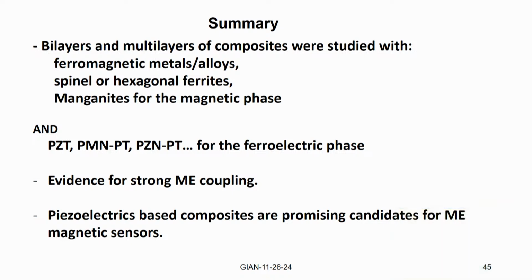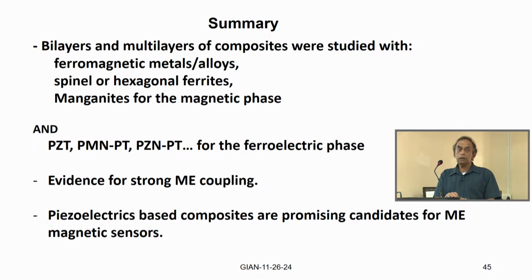To summarize, I discussed the magnetoelectric bilayers and trilayers based on PCT, PMN-PT and pure piezoelectrics, with a variety of ferromagnetic phases including 3D metals and alloys, spinel and hexagonal ferrites and lanthanum manganate. All of them show evidence for strong magnetoelectric coupling. So at the end of the day, you get the feeling that for many applications, you are better off using piezoelectrics rather than ferroelectrics. Right, thank you.